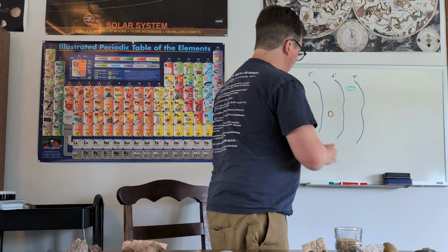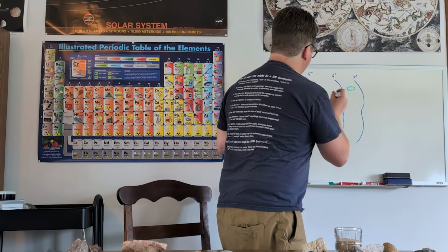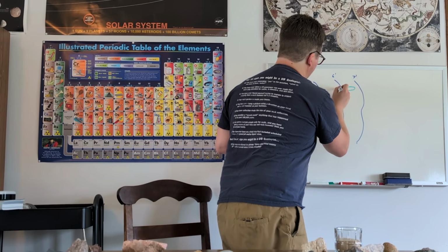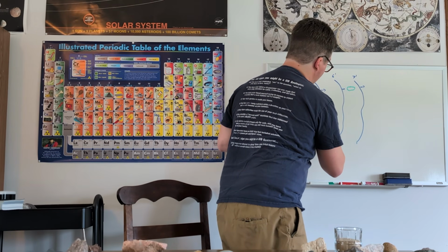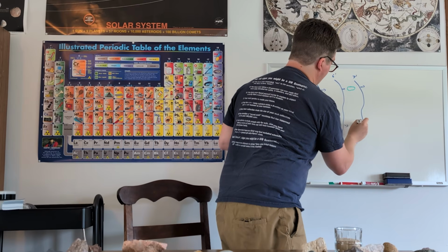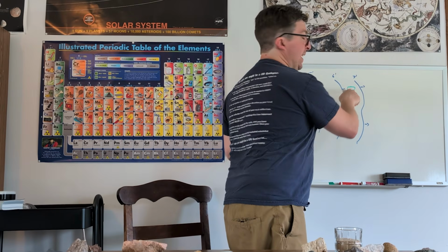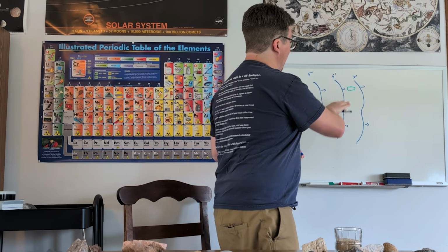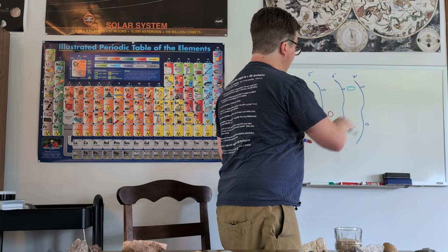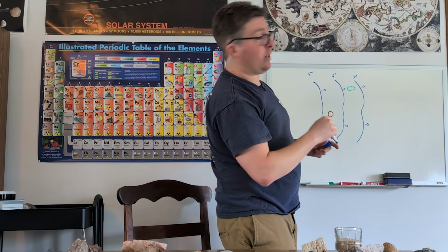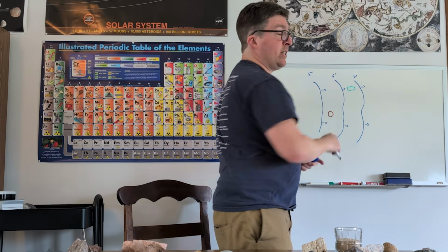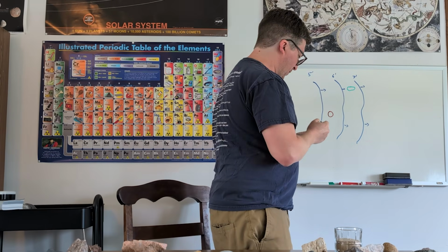Well, so the groundwater flow direction is going like this, right? So nothing to worry about, right? All the nasty stuff from your septic tank is going to flow over here, and it's not going to go against the direction of groundwater flow. It's not going to flow upstream to your well. So, hey, you're safe, right?